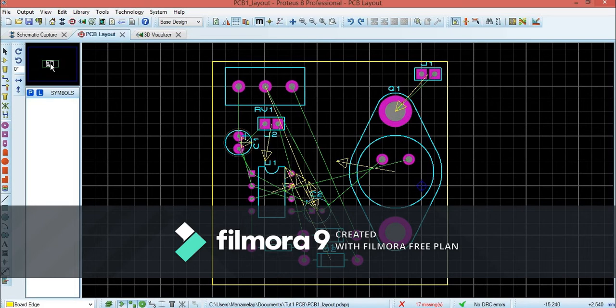Now I want us to begin routing. To route, we go to track mode. Remember, when you're placing the components, we are in component mode. This is the package mode to be able to see the packages for all the components and the sizes. Normally, almost all software uses inches instead of centimeters and millimeters, but mostly South African metrics use millimeters. Okay, now let's go back to the track mode and begin routing.